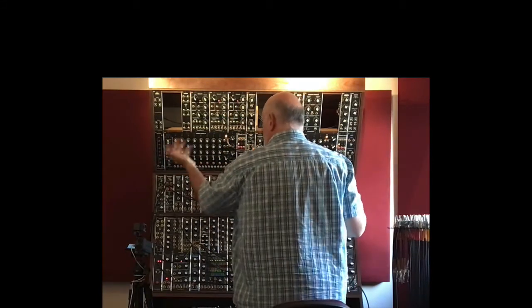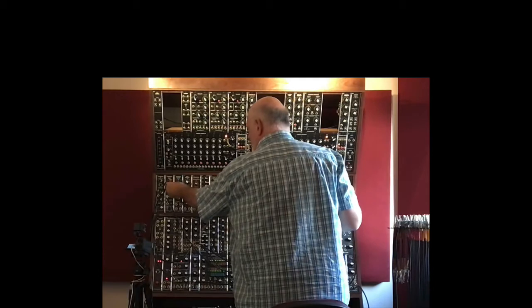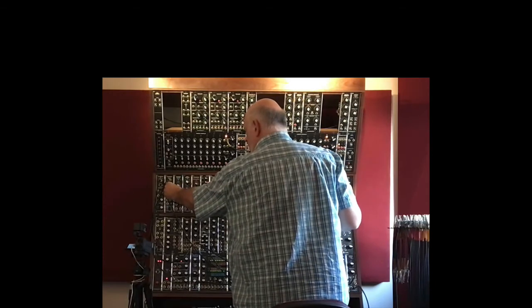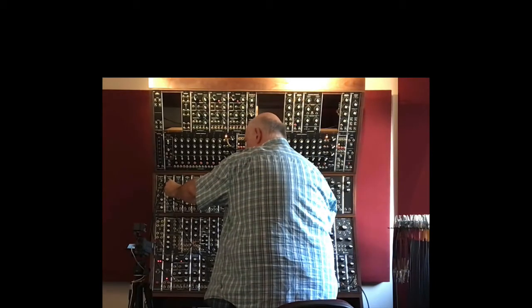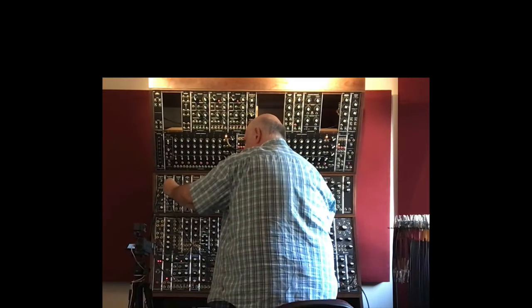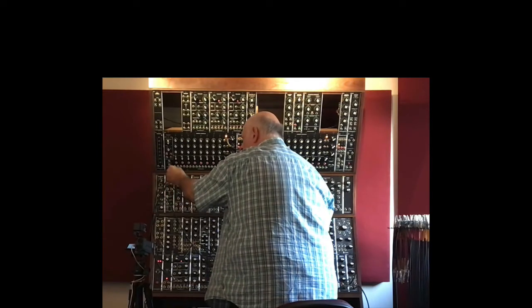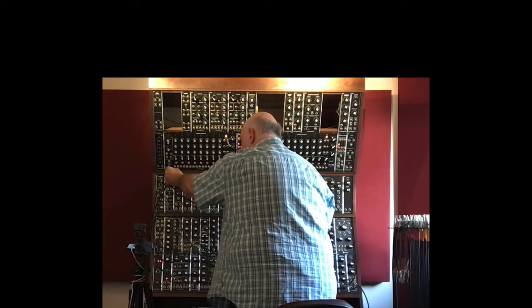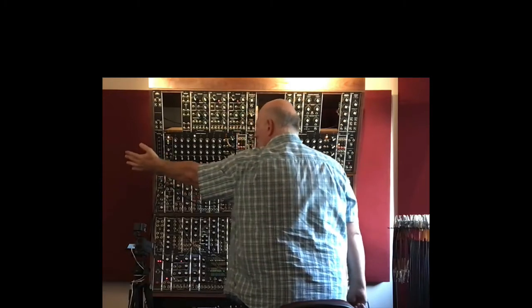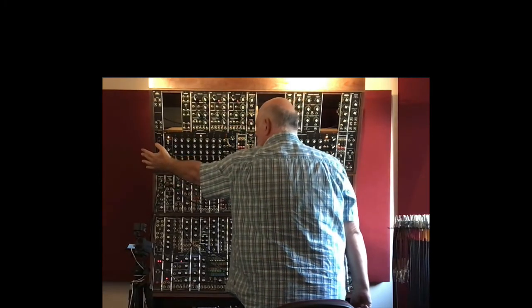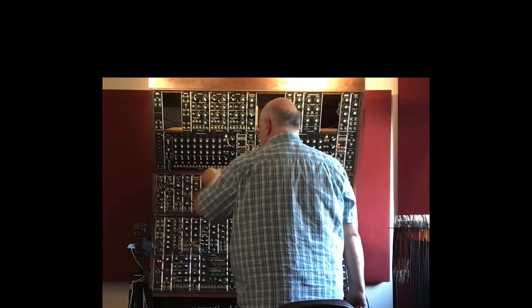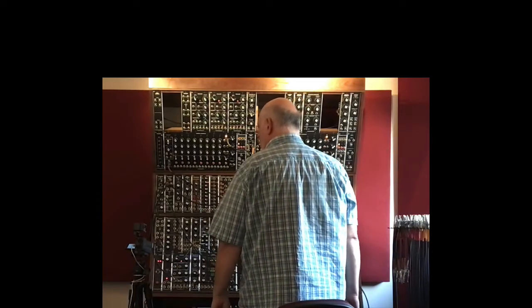doesn't matter what the notes are, just make something. Then take the gate output of the MIDI interface that the keyboard is sending gates from, unplug it and plug it into the oscillator output of the Q960, hit play. Now you're ready to actually do the example capture.